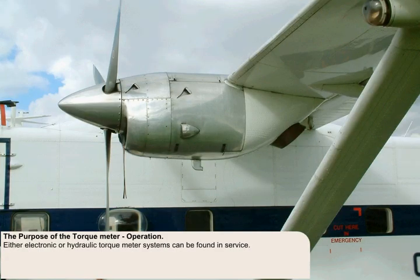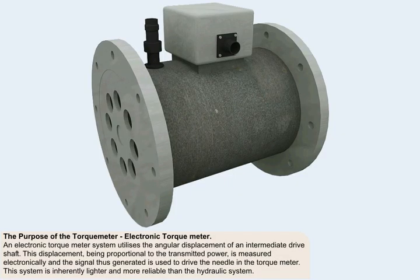Either electronic or hydraulic torque meter systems can be found in service. An electronic torque meter system, such as the one shown here, utilizes the angular displacement of a drive shaft, which is placed between the engine and the propeller drive. This displacement, being proportional to the transmitted power, is measured electronically, and the signal thus generated is used to drive the needle in the torque meter. This system is inherently lighter and more reliable than the hydraulic system.